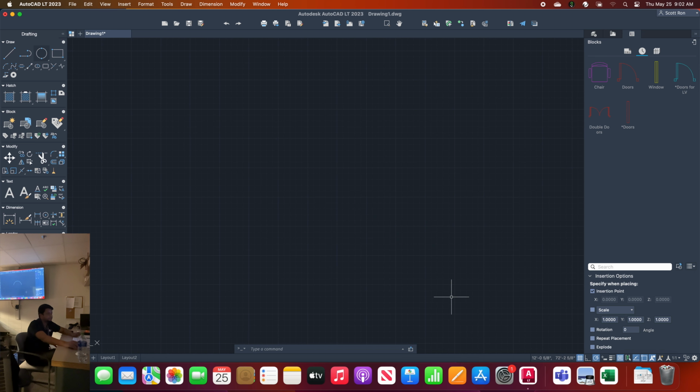Simple? Okay. But like I said, in AutoCAD, you'll see these arrow marks, which are like a drop-down menu when you click and hold on it. So if you click and hold, there's a whole bunch of ways to draw circles. That was the very first one. There's circle center diameter, where you specify the center and you give the radius, or you give the diameter. Whichever works best for you, use that.